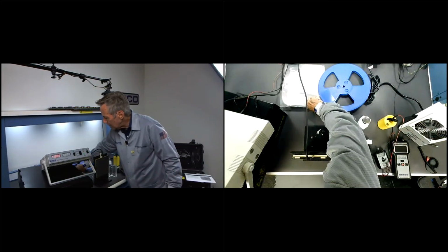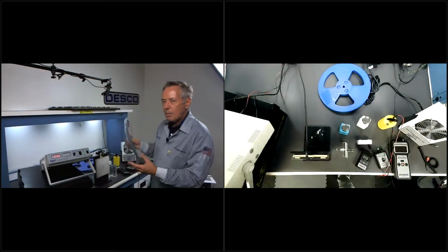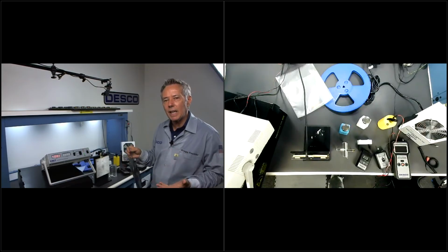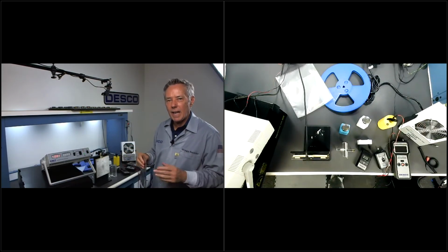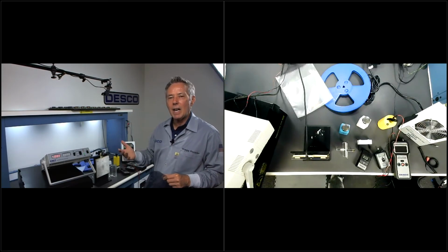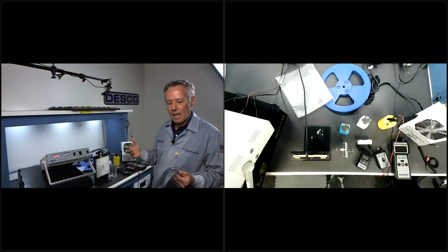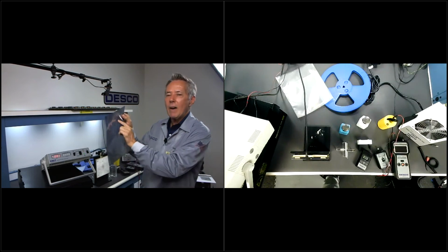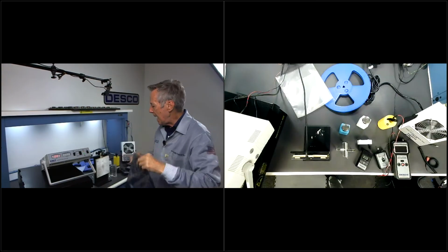The other thing we can show you too are ESD packaging materials. I used the term static shielding. In order to have shielding versus, say, a pink poly or an anti-static bag, you have to have conductivity or metal of some kind. So when it comes to a static shielding bag, we have a dissipative outer layer, we have a dissipative inner layer, but then we have a metal layer of aluminum on the inside. It's that aluminum that keeps the charges from getting in that bag.